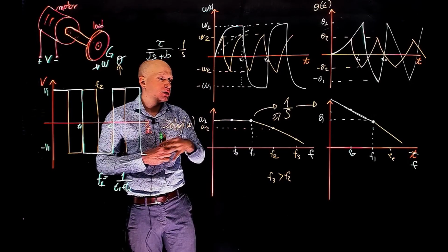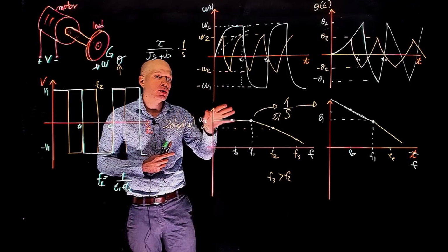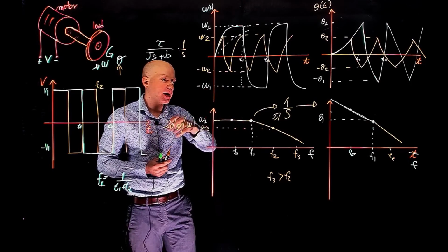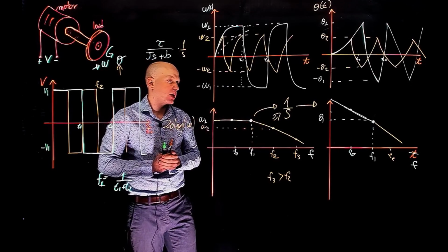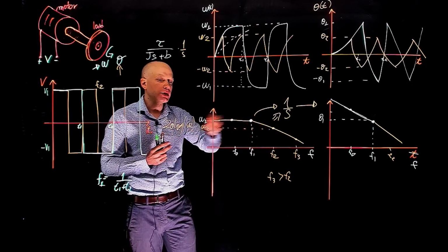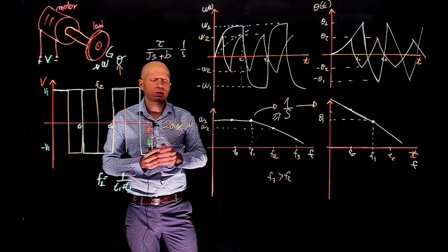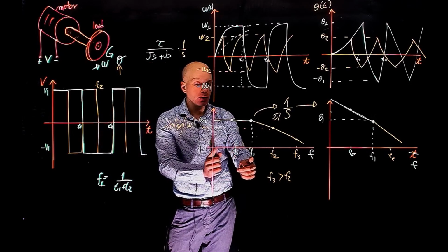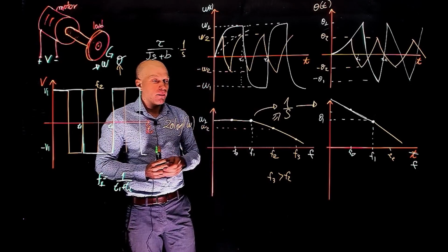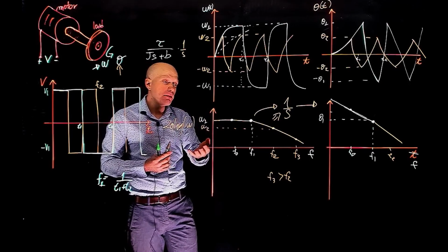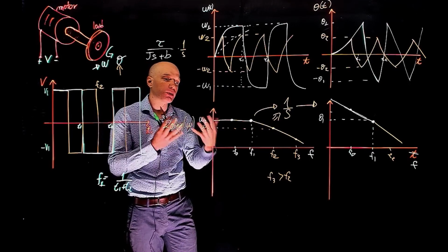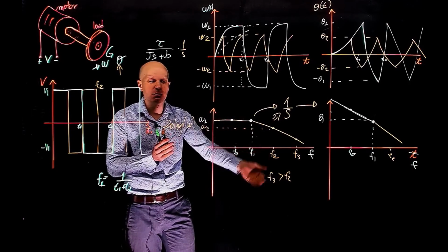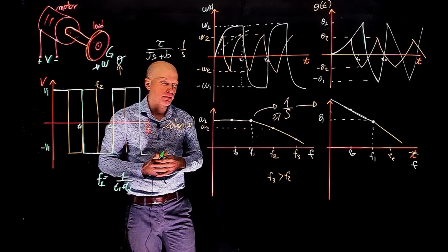The reason is that their Bode plot tells you at what frequency those components will operate. Imagine that you want a robot to do some sort of pick and place task, and you want that pick and place to occur at a frequency of, say, 10 Hertz. If your cutoff frequency here is too low, say 1 Hertz, then you will have to increase the magnitude of the input by a very large amount in order to get the displacement you want at the output, the magnitude of that displacement or speed at that particular frequency.